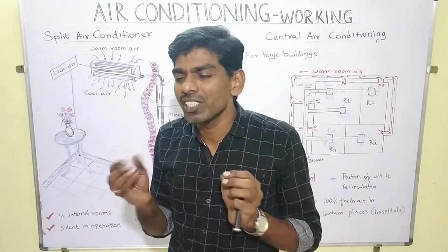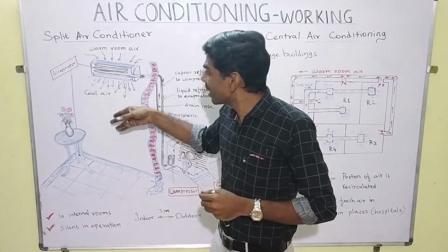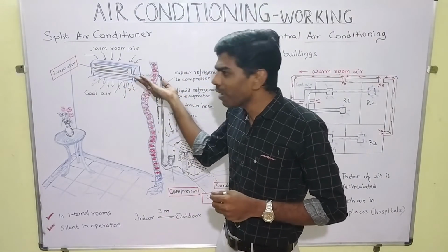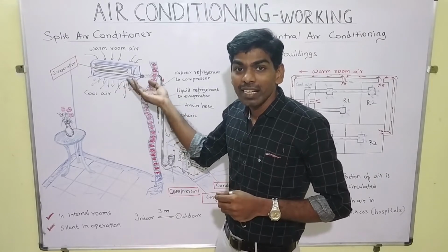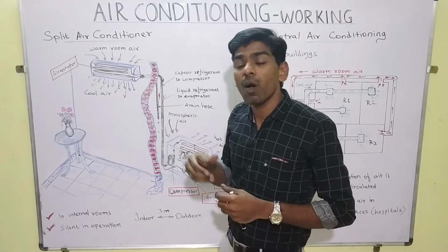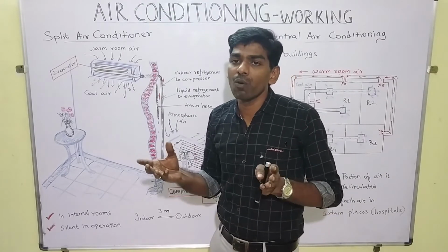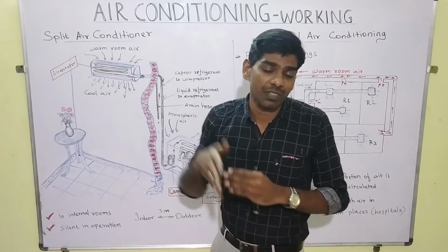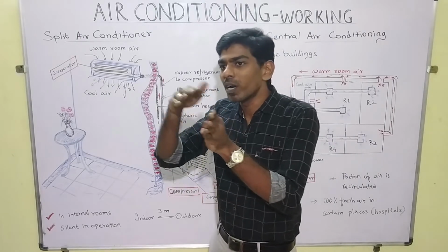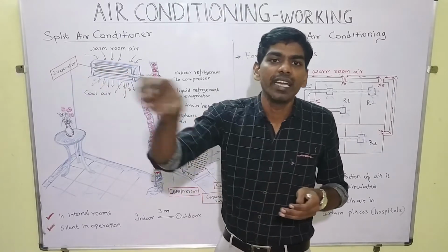Here it is very much silent because we don't have the compressor within this. If we stand here, we will just have the fan and the evaporator, nothing more than that. We don't have a compressor, which creates noise. It is held away. And also we can place this anywhere we wish. We can mount it even on a wall which is not adjacent to the atmosphere. It is not a must to mount the system on a wall on the exterior side. So it's not a must. You can even hold it in any place.